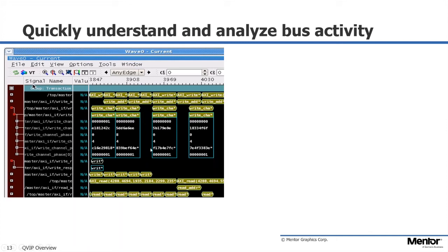This is the Visualizer wave window. You get the exact same with the traditional Questa debugger, that you can drop all of those transactions into the wave window, which basically what you see here is, on this AXI bus, I did a write to channel 1 with these parameters here. Here I did a write to channel 0. There's another write.